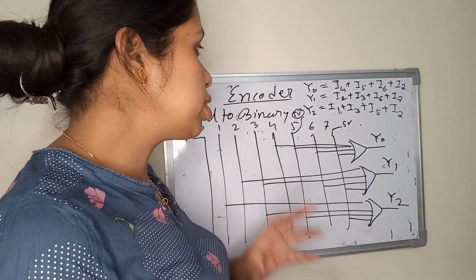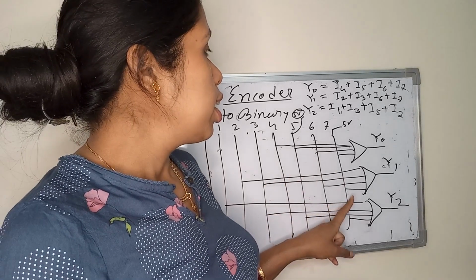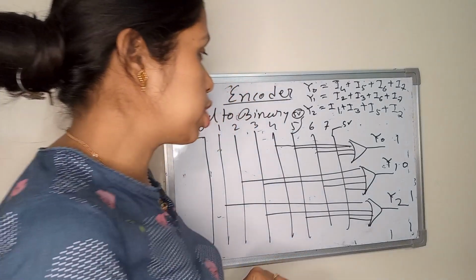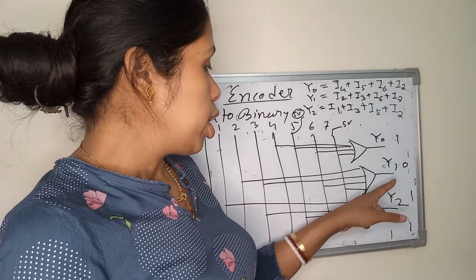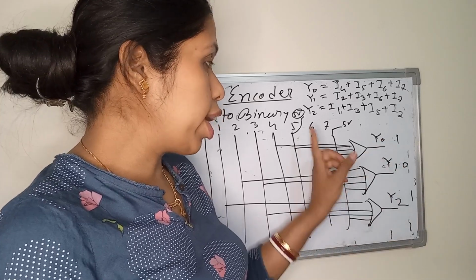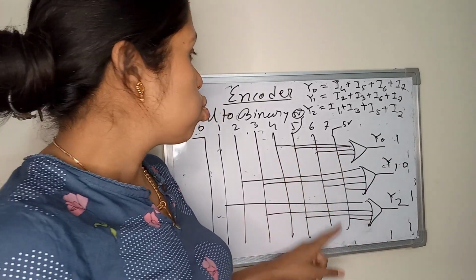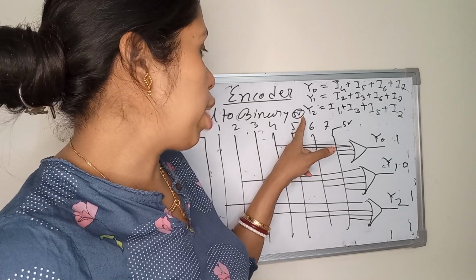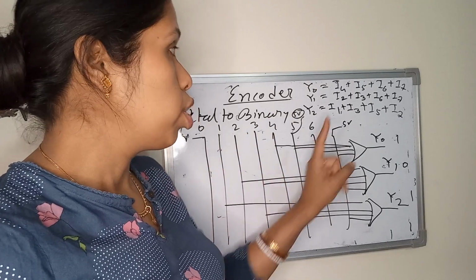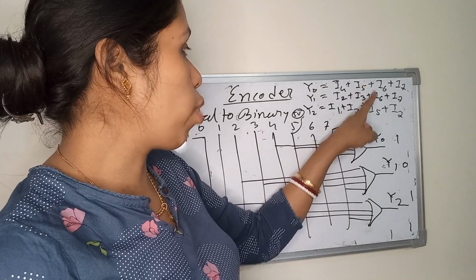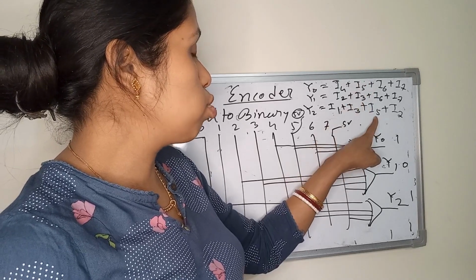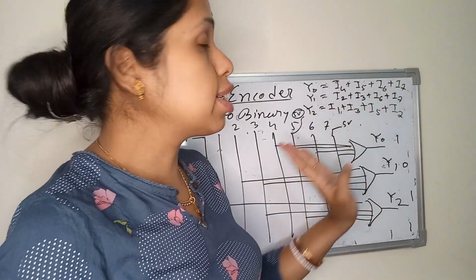I5 is connected to 5 volt, so I am sending logic 1 through I5 and the other bits should be 0. Now you can see I5 is present in Y0 and Y2. That means this I5 is 1, and the others are 0.